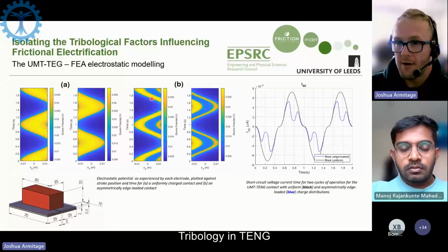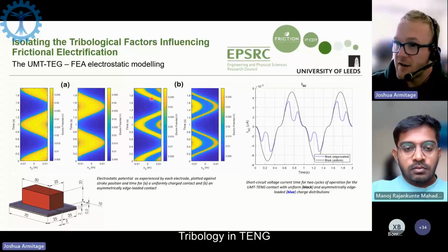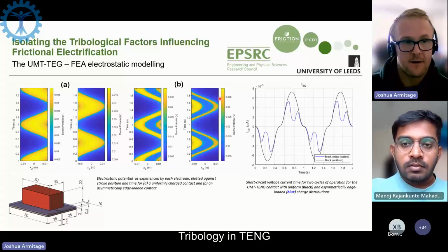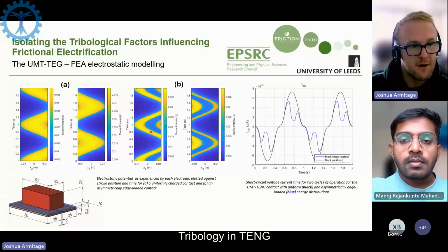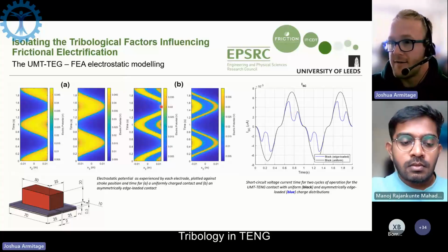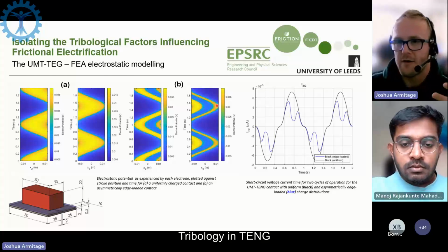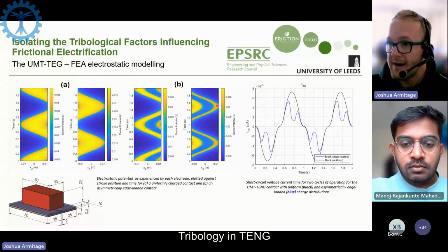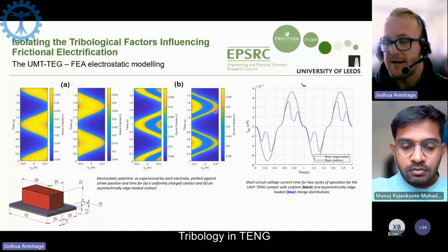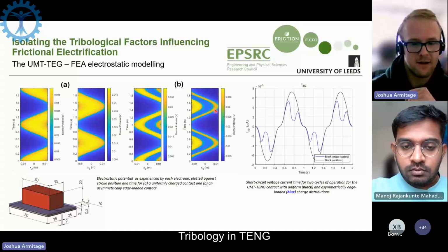It's showing that the block, when we bring it into contact, is actually edge loaded, and in some circumstances it is asymmetrically edge loaded. So you can see here where one edge of a block, possibly like this side here, has a higher density of charge than the other edge of the block, and in the middle we're not actually getting as much contact, or as much contact pressure, as we would expect. Which makes sense when you have plate-on-plate contacts. You normally tend to see the edges of that contact having a higher contact pressure due to the edge loading effect, essentially.